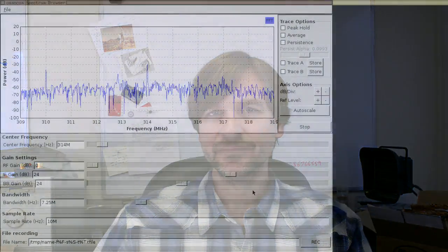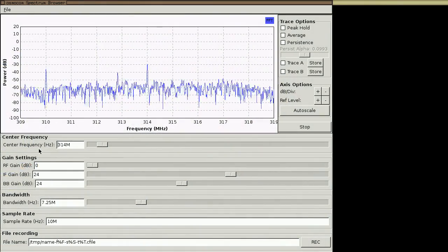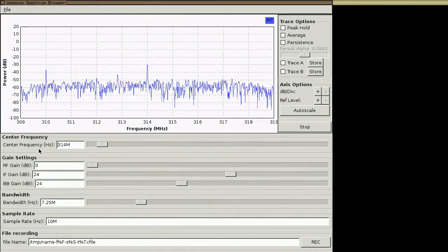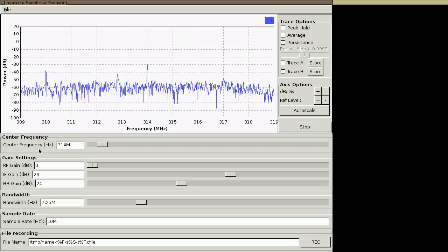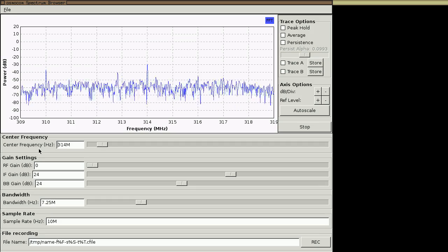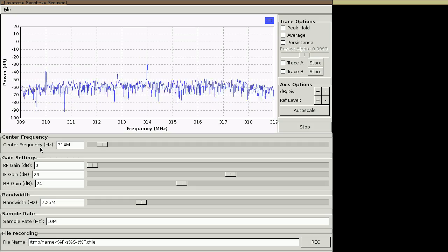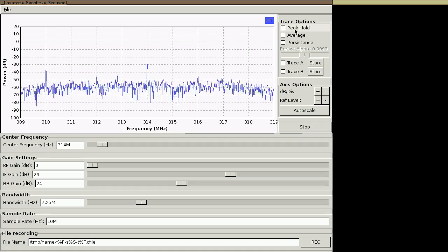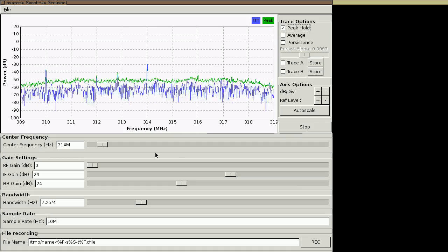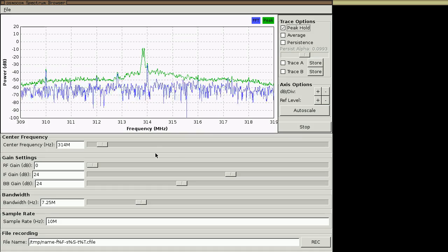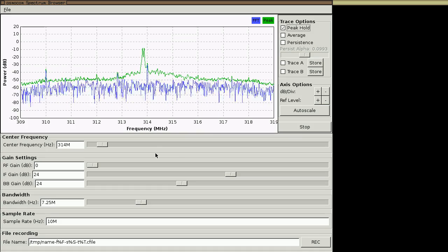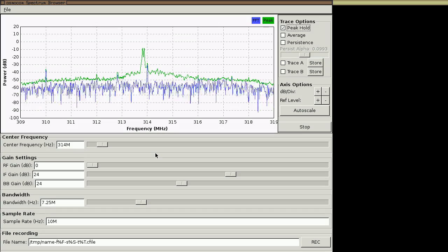And I'd like to take a minute to show you the effect of the anti-aliasing baseband filter in HackRF One. I'm using Osmocom FFT just like I did in lesson 9, and I have that car key again, the remote keyless entry device. So if I press the button on the car key, you can see the transmission show up. I'll turn on peak hold here, and I want to show you something about the shape of the analog baseband filter. That's the anti-aliasing filter in HackRF.